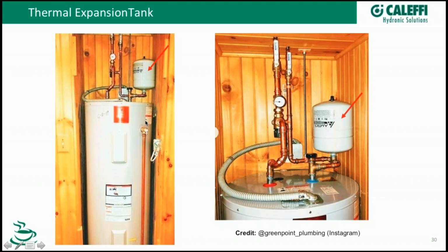And the other thing on this valve, when you go to replace a valve like this, you've got to know the size. On this little tag, it's going to tell you the pressure rating of that valve, typically 150 on a domestic tank. It's going to have the temperature, 210 degrees, just under boiling. And also it's going to have a BTU rating on it. So you need to know the BTU rating if it's gas fired on the burner there, or do the conversion on the electric elements here, and make sure that valve is sized for whatever the burner can produce for the discharge of that valve.